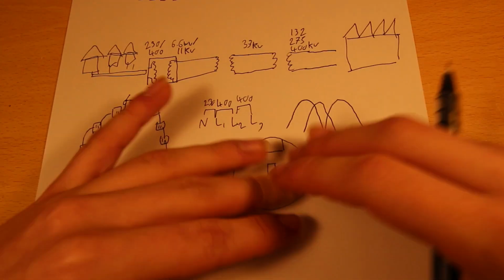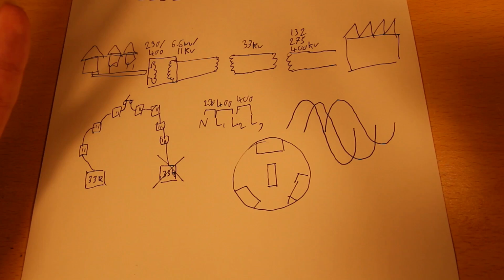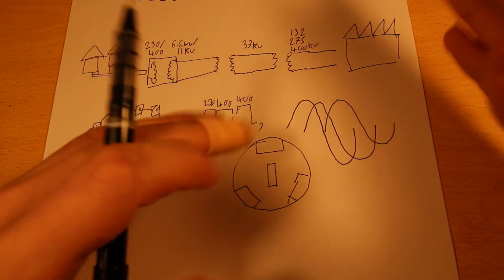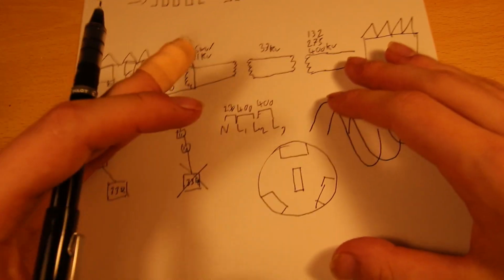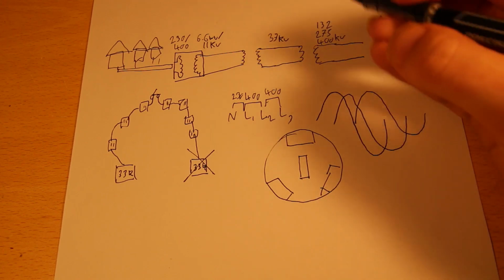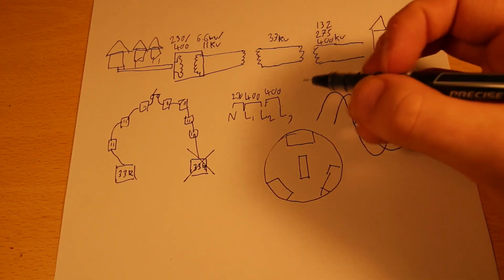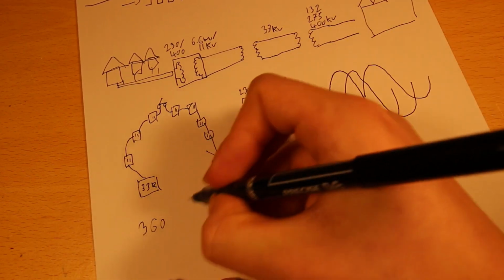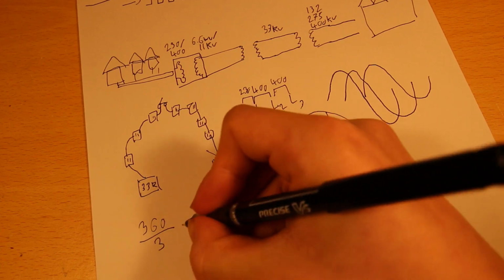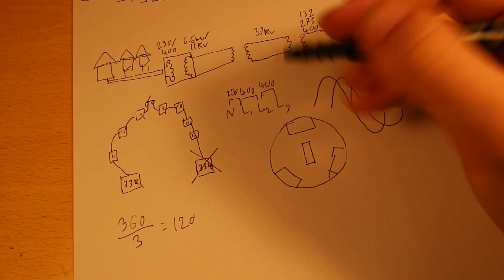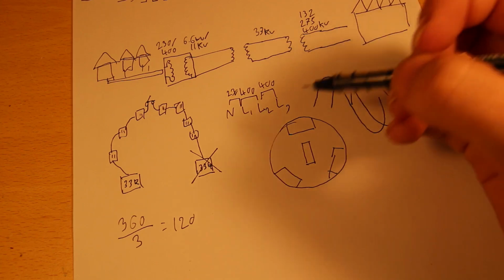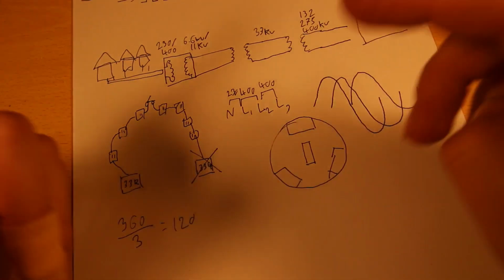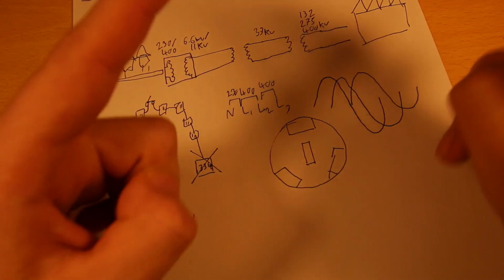You have 3 phases, that's kind of the accepted standard now, but that's not the limit. You can have as many as you want, really, within reason. There is no theoretical limit on it, as far as I'm aware, but there are practical limits. Say on 3-phase, it's a 120 degree phase shift, because 360 degrees of rotation divided by 3 phases equals 120 degrees. If you wanted, you can have 2-phase, which is 2 phases 180 degrees out of phase. Sometimes 2-phase power is 90 degrees phase shifted, which is kind of 4-phase, but just missing 2 of them.